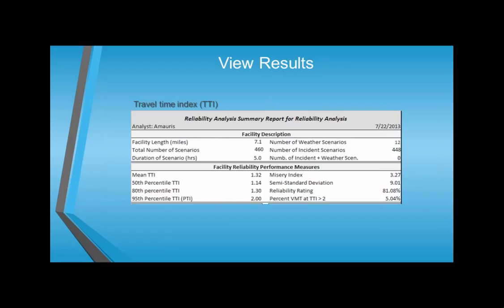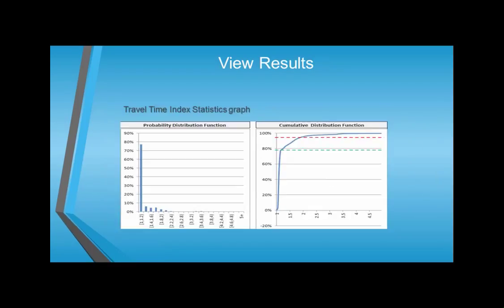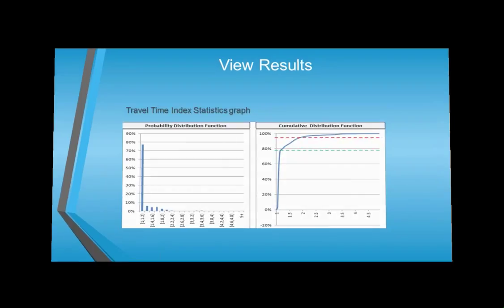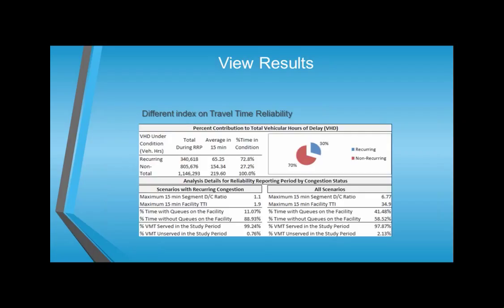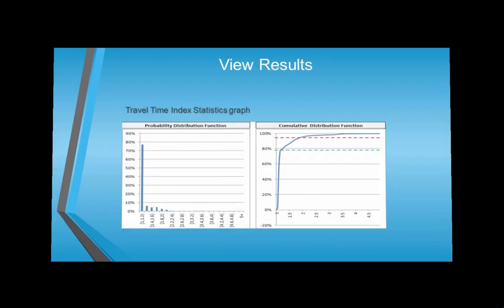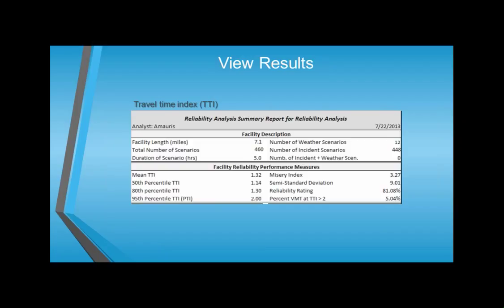We first use the annual average daily demand volume, but if we don't have that information, we can use a date that represents the annual average daily volume, which in our case was January 3rd, because on that date we didn't have any incidents and the weather was good. And that, in our consideration, represents a good annual average daily volume. Then we take the average of all the Mondays of January, and we divide that average by the standard day we're choosing in the first step, and this is how we get the daily demand pattern.